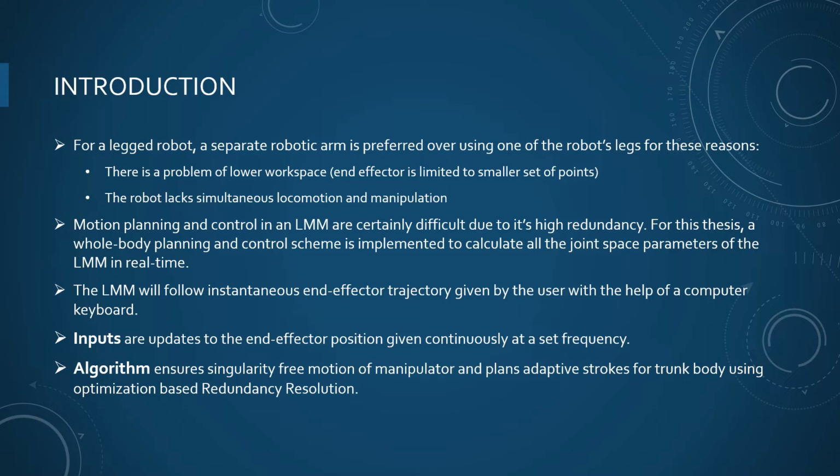Inputs are updates to the end effector position given continuously at a set frequency, and the algorithm ensures singularity-free motion of the manipulator and plans adaptive strokes for the trunk body using optimization-based redundancy resolution.